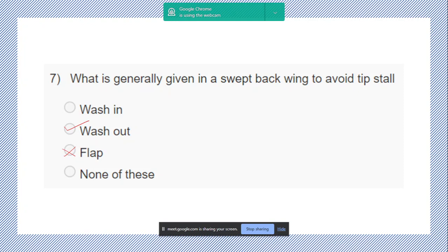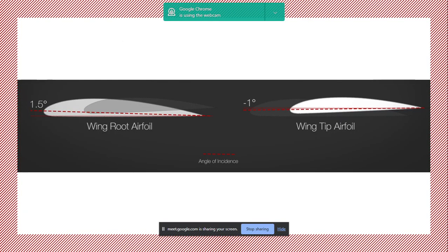Correct, absolutely right. What happens is that the incidence angle at the wing root is higher than the incidence angle at the tip. If this is your fuselage reference line, your wing setting angle at the root chord is higher as compared to the tip. At the tip it is either negative or lower than the wing root. The reason that he said is absolutely right.